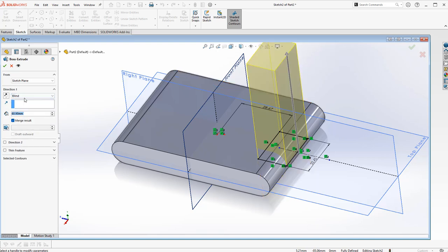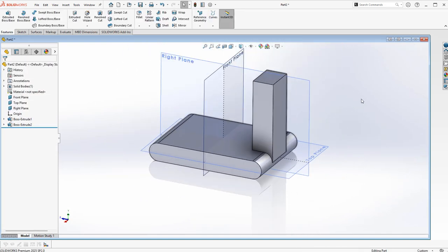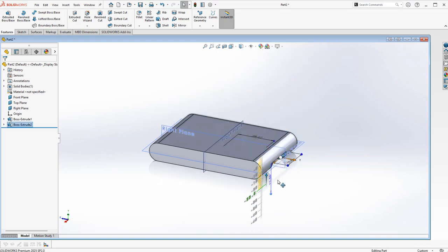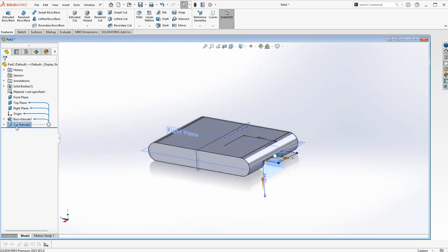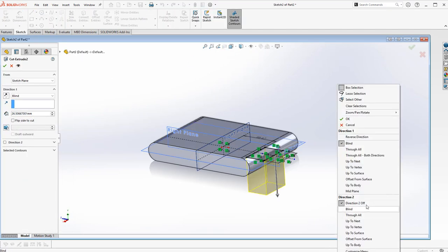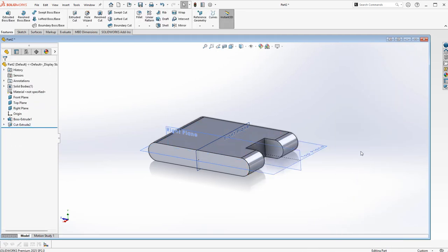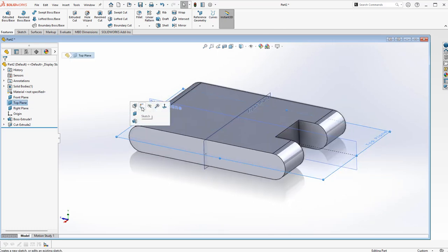If I make a mistake and extrude a solid where I mean it to be a cut, you can just double click on the thing and drag it in the other direction and it converts it to a cut. I've never seen a SolidWorks user know that one. There's a lot of cool little tricks that can be had if you were to take a SolidWorks update training. The software has changed quite a bit in 20 years, and people tend to think they know everything about the tool.